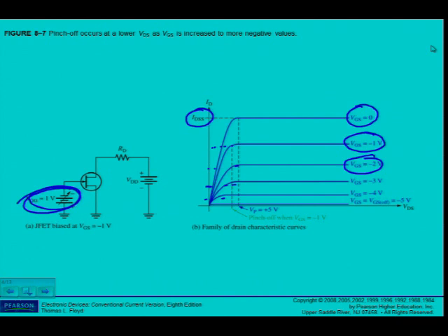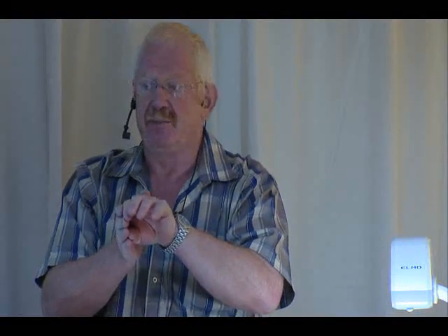Alright, until I've reached the point, as we've discussed, VGS equal to VGS off. What happens at this stage? That's when the two depletion regions touch each other and the channel is completely closed and no current flows through the device anymore, né? So remember again, no biasing, maximum current, because then the channel is open. As I start biasing, I'm starting to close the channel down until it's completely closed down and ID becomes 0.